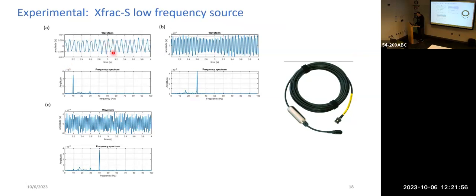And that is the waveform and the spectrum recorded when the source is working at 10 hertz, 20 hertz, 30 hertz, and 40 hertz. And you can see from here, we have some small peaks. They are the background noise of the building AC system and the pipe system. We cannot remove it because the water tank has a very strong coupling with the land.